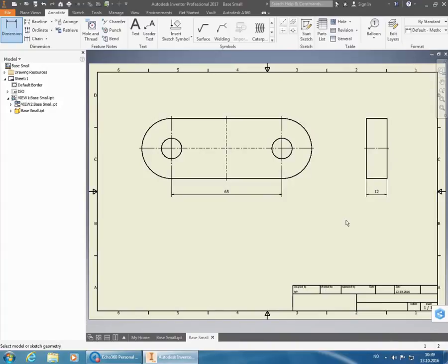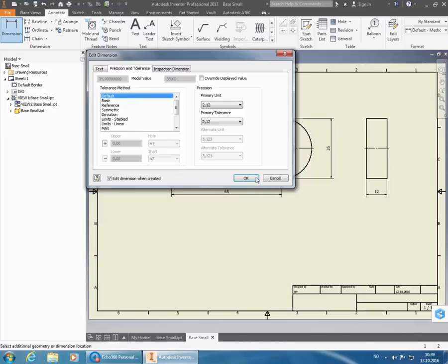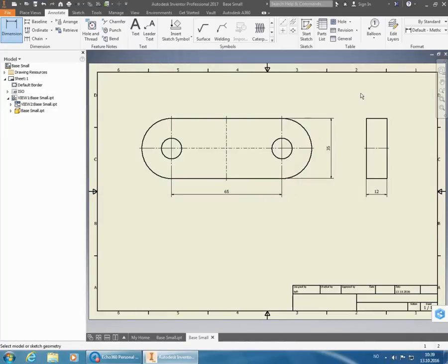And then we can give the dimension across from the bottom to the top and over here. So then we get the 35 in width across it. And now the only dimension that we're missing right now is the diameter of the holes. But we're going to use the hole and thread function to set that one instead.